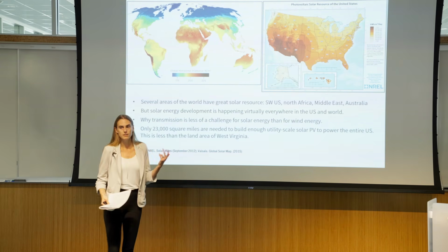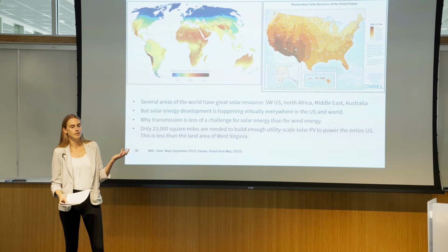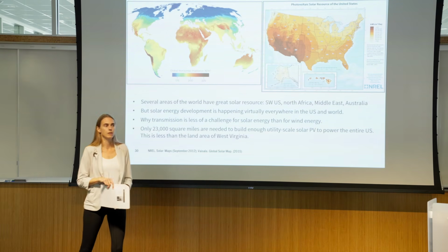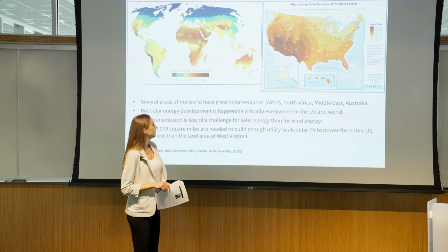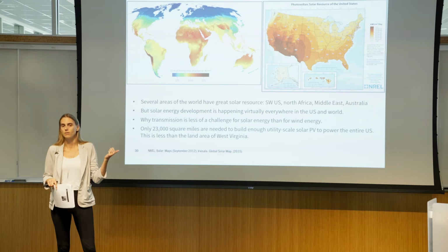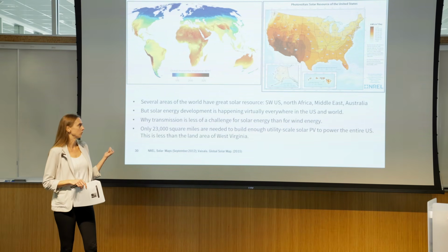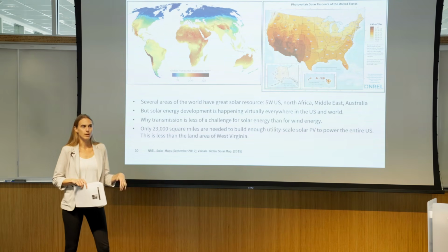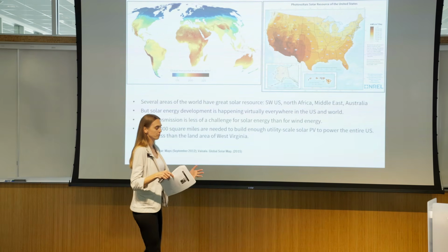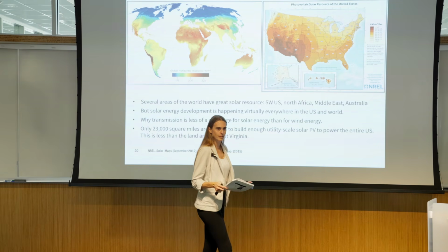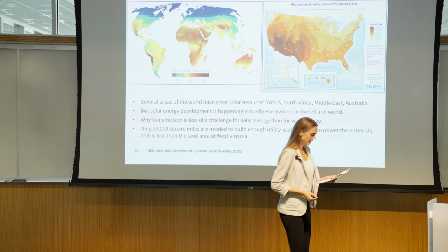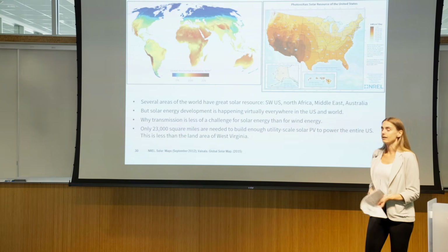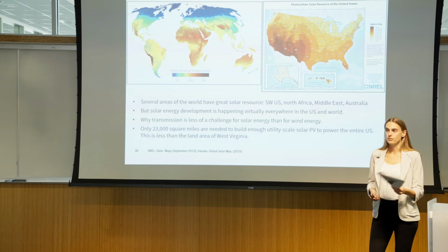And this is important because different solar technologies vary in terms of whether or not they can take advantage of diffuse radiation. Anything that uses reflectors can't take advantage of diffuse radiation. And that's why you see a lot of the concentrating solar power projects built out in the middle of the desert that has the most direct radiation, right? You don't have a lot of cloud coverage in the desert. Solar PV, for example, can take advantage of both direct and diffuse radiation.